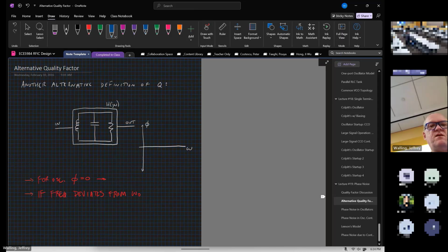If we have the parallel resonant circuit, we can also measure the phase response of the circuit. We know for this particular circuit that the phase should be positive at low frequencies and negative at high frequencies. The voltage should be leading the current at low frequencies and lagging the current at high frequencies.